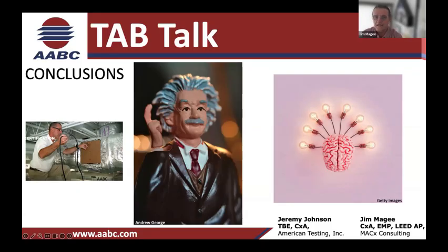As the commissioning provider, I know, and designers should know this too, where they've made changes. They couldn't fit the sixth large circular diffuser into the auditorium, so they went with 5. So the first thing I'm going to do is go look at that TAB report, a system that you might not have been able to get on those diffusers to begin with, and see: are they showing 5 or 6 diffusers there? Right away, I know what these guys are doing. So that's a couple things I'm looking at.